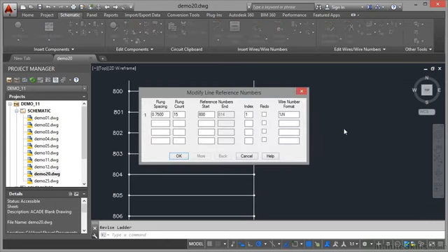You'll notice that it comes up with the rung spacing, the rung count, and the reference start that we've already got in our drawing. It'll recognize that. And any other references that we've got to ladders in the drawing, I can specify in the empty boxes. But it's this particular reference that we need to look at. Now, all I'm going to do is change the reference start number. I'm going to change that to 900, and that's all I'm going to change.